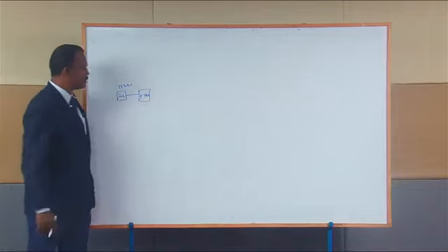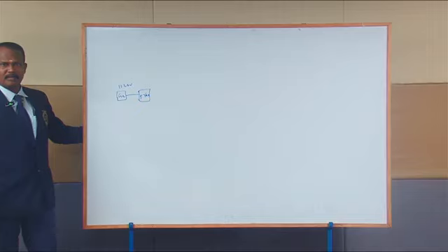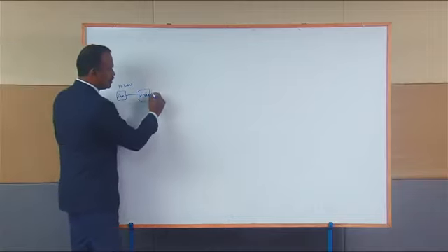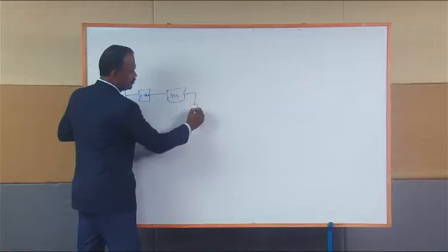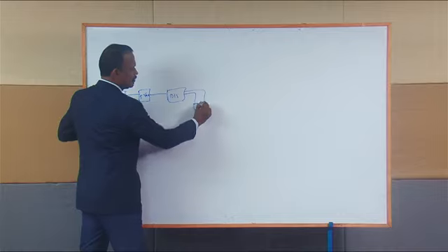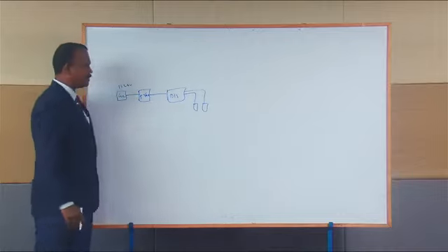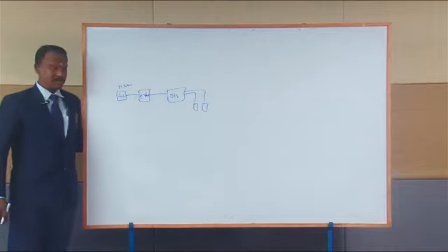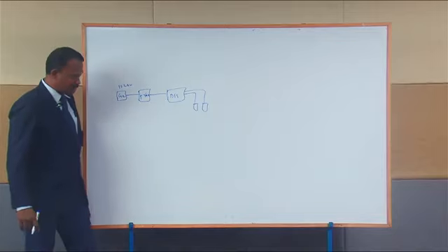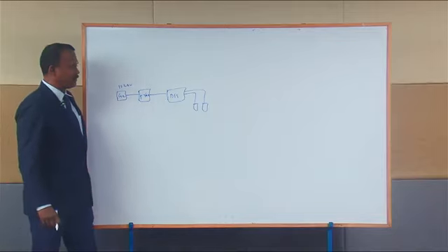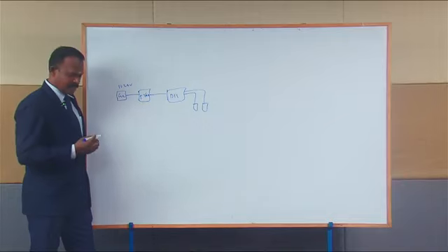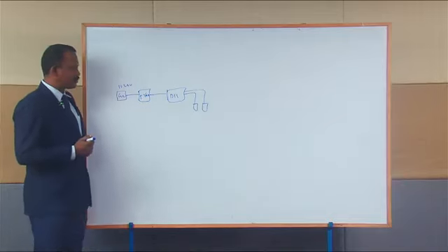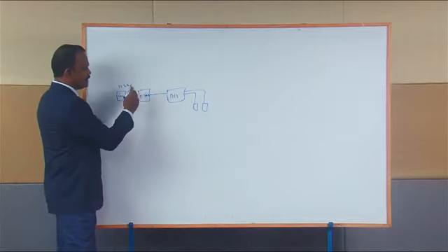If you transmit the power at 11.2 kV through a long transmission line to the distribution station where we connect all the loads, it is going to be a big problem, because the losses will be huge when transmitting power over a long distance at very low voltage levels. So for this situation I need a transformer.